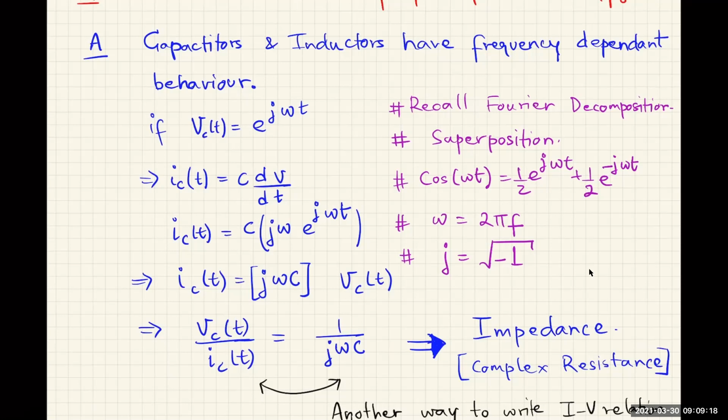We can take it further and take the limit of the period to be infinite, and that way you can, in fact, also decompose any arbitrary non-periodic function into a spectrum of frequencies, a spectrum of signals with all different frequencies. Right, so that's Fourier decomposition, basically saying we can decompose any signal into different frequencies.